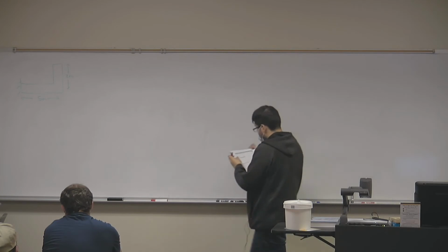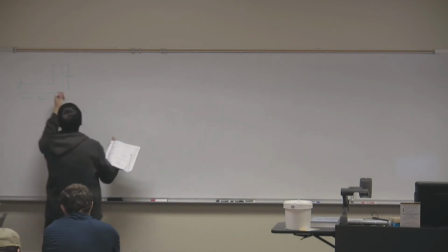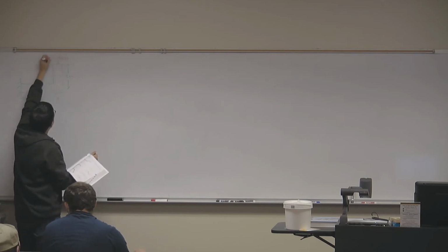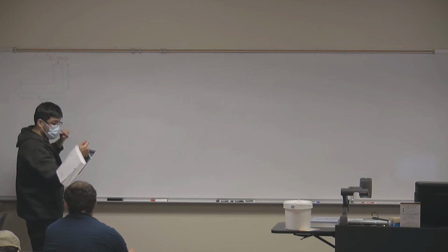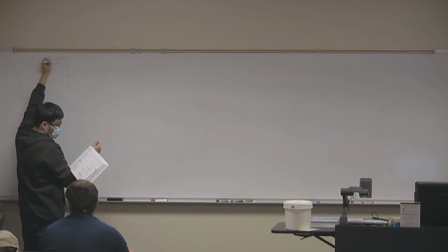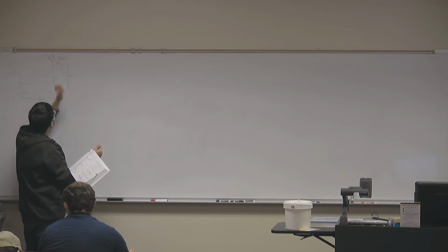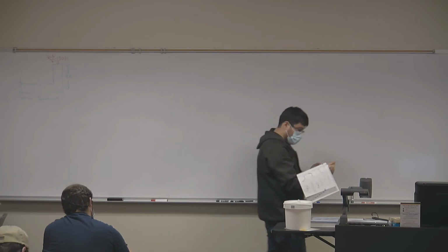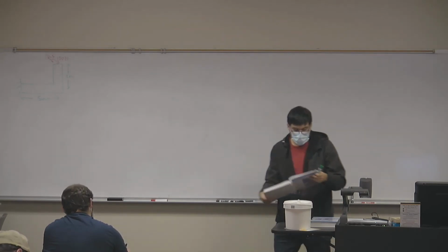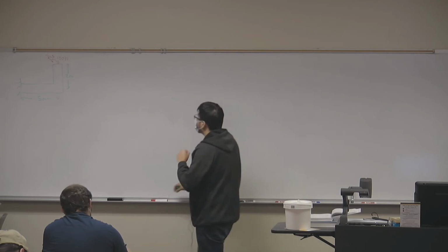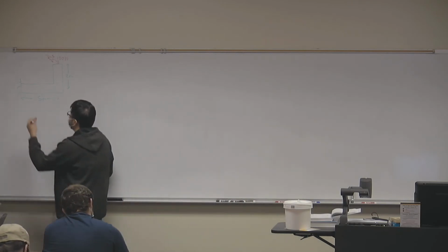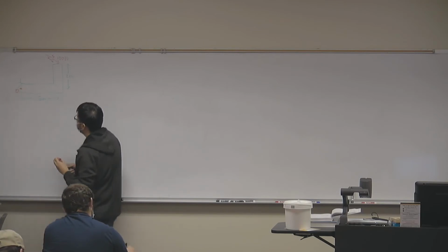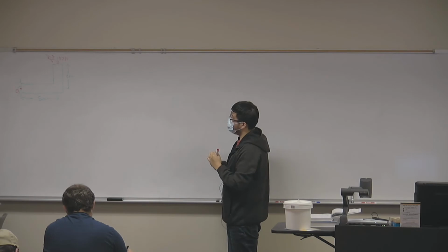We have a force of 100 newtons acting at the end of our block with a slope. I'm not giving you an angle, I'm giving you a slope of 4 horizontal for every 3 vertical. Okay? Now the question is, what is the moment that this 100 Newton force causes about my origin point if I define my origin right at the wall?